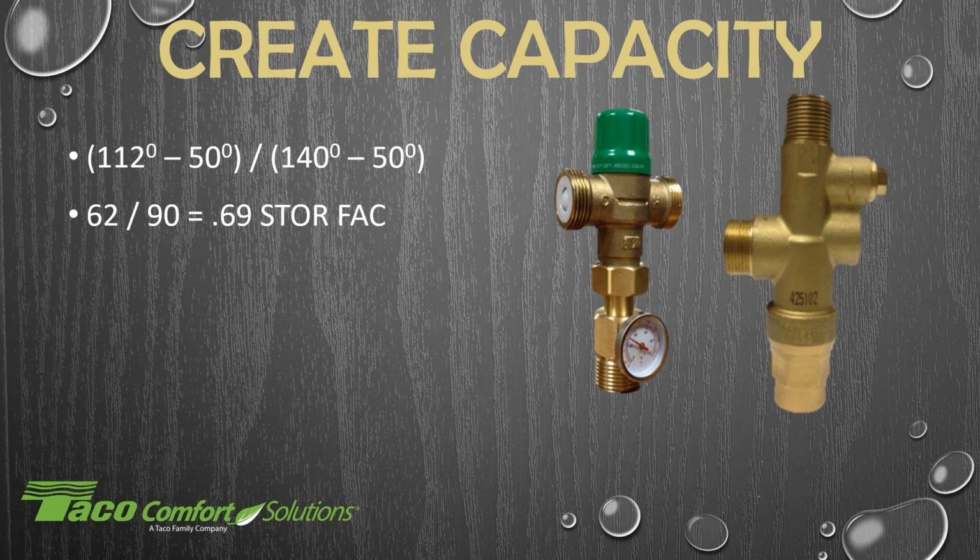Now we want to apply that to the usable capacity of our tank. If you have a 45-gallon tank, you do not have 45 gallons available. What you have is around 70–75% available, because in a standard tank-type water heater, right down the middle of it, you've got your flue pipe, if you're looking at a fuel-fired water heater. If you're looking at an indirect, we have a coil, and that's also going to take up some volume of water. And then of course, as soon as you start drawing off of it, we start introducing 50-degree water back into that tank. So we only have around 70–75% capacity.